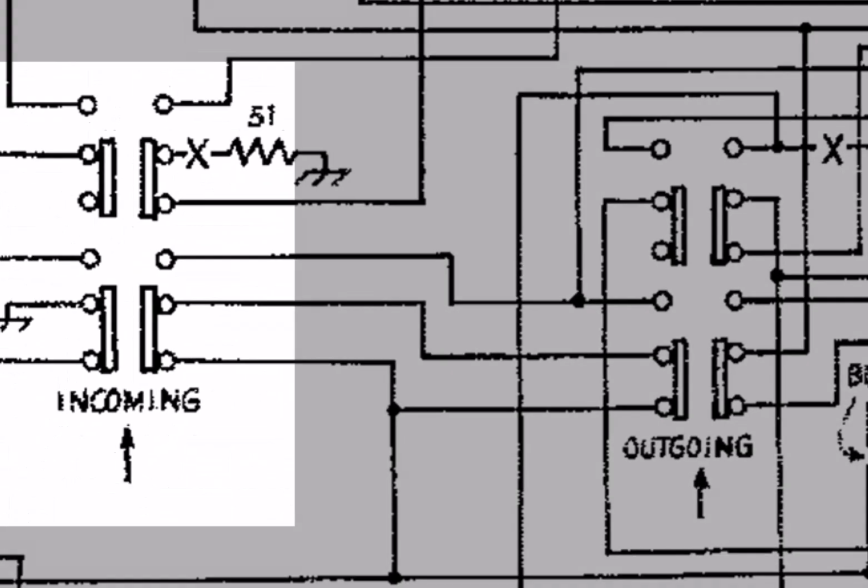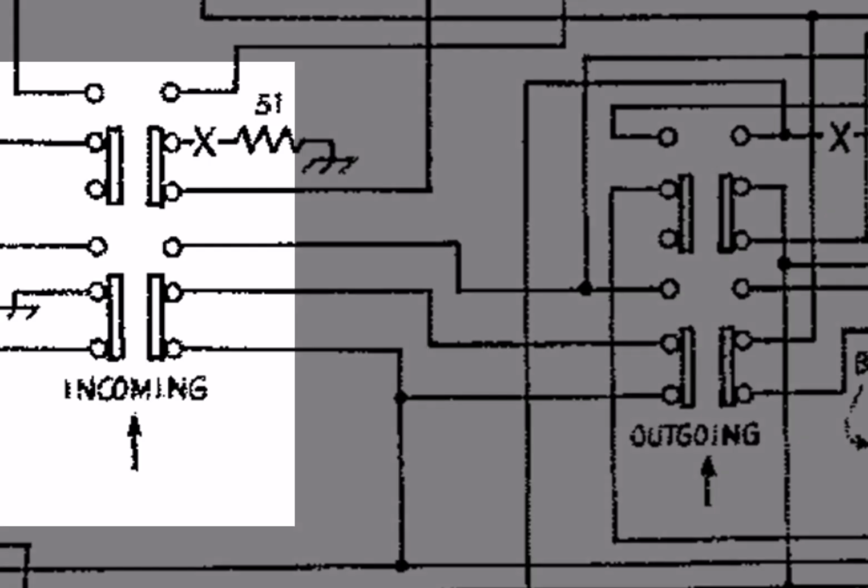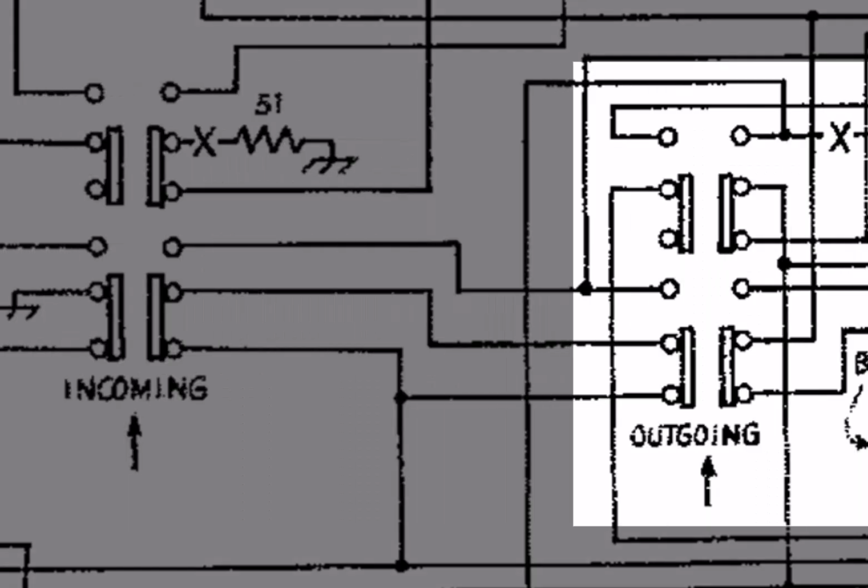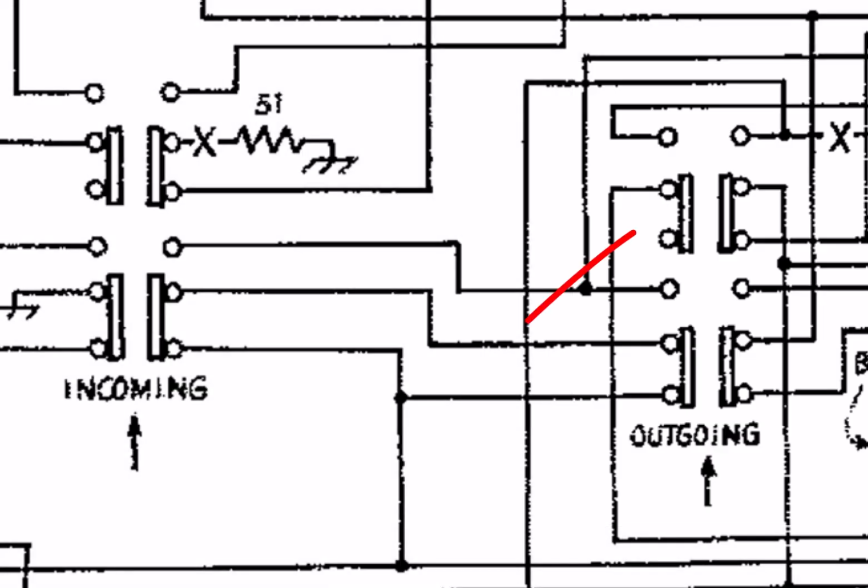These two front panel switches I showed earlier are the radio buttons for incoming and outgoing transmission, and both are shown in the non-selected state. Each button has 4 shorting blocks that connect 2 of its 3 terminals. Mechanically, the radio buttons are mutually exclusive, so the device is either in the sending mode, receiving mode, or it's idle when neither button is engaged.